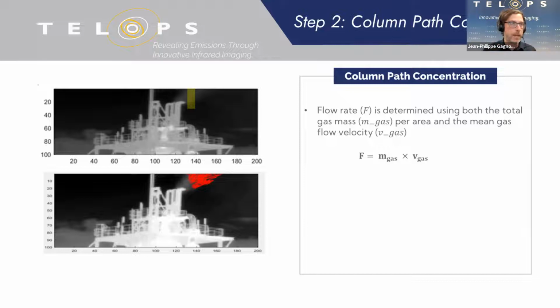So let's say for that day, the wind was 5 kilometers an hour. Sometimes we approximate the gas displacement velocity by 5 kilometers an hour. Then we multiply the amount of grams in that rectangle by the wind, or by the gas displacement velocity. That will give us how many grams per unit time cross, or enter and exit, that imaginary yellow rectangle.